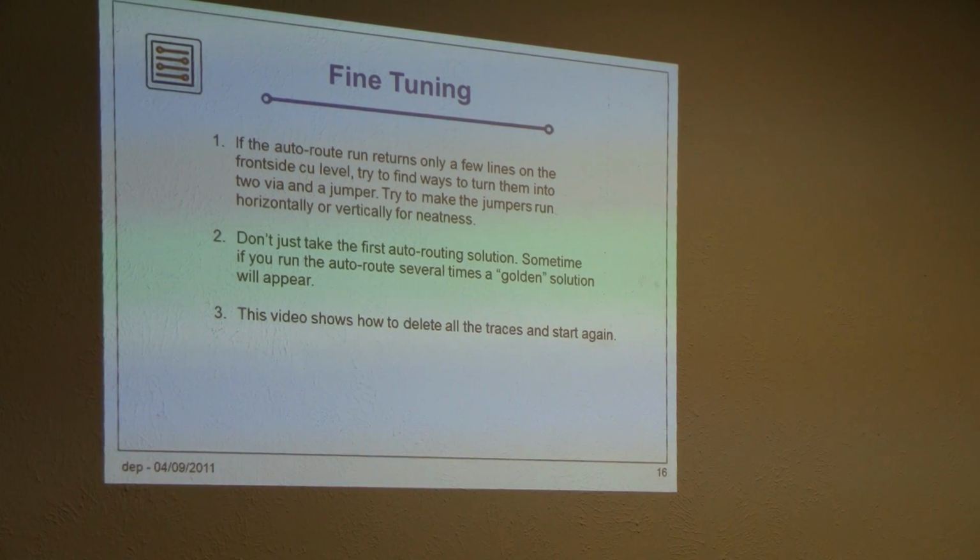That just means that if a wire goes from this node to this node, you delete that wire, go to your backside copper, pick up here, and go to a location, you create a via, and via happens to be V. Oh, it's clever. That'll automatically drop you to the top level, and you can trace over to where you want to go, create another via, and it'll drop down to the back level, and then you go to the component that had the other side of the connection.